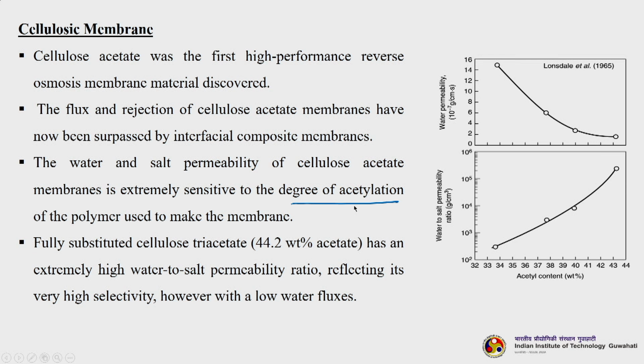We have understood what the degree of acetylation is when we discussed cellulose and its properties. Fully substituted cellulose triacetate, CTA, almost 44.2 weight percent acetate, has an extremely high water to salt permeability ratio, reflecting its very high selectivity, however, with low water fluxes. So, the selectivity has increased, but the water flux has decreased. This is a Lonsdale study from 1965. You can see that water permeability is decreasing with acetyl content, however, water to salt permeability is increasing.